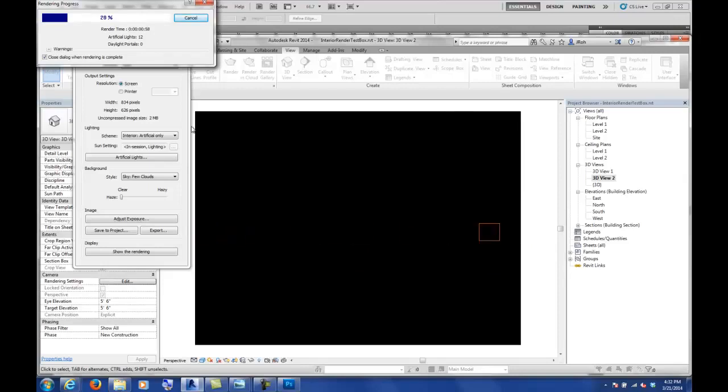So if I made a change to masonry brick and I kept the same name of masonry brick and I didn't change it or do anything unique to it, when it goes up to the cloud, it's going to override it and change it back to what it was supposed to be originally. So if you went around and tweaked all these materials and added all this stuff to it, as soon as it goes to the cloud, if you didn't do anything with those names, it's going to be basically overwritten.